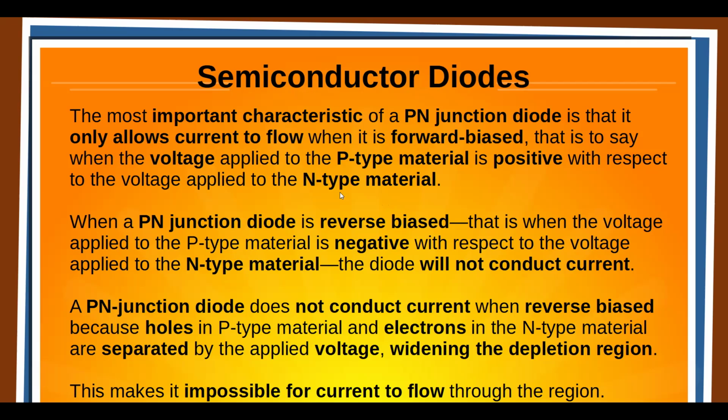And we'll talk about that probably as the next diode. Yeah, it doesn't normally conduct when it's reverse biased unless you get up to a high enough reverse voltage. When you apply a reverse voltage, what in effect is happening is that depletion zone we talked about gets wider.